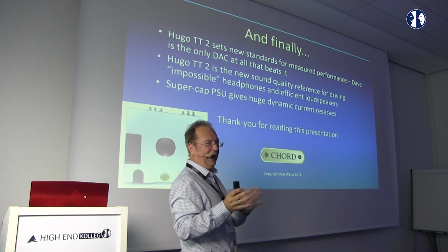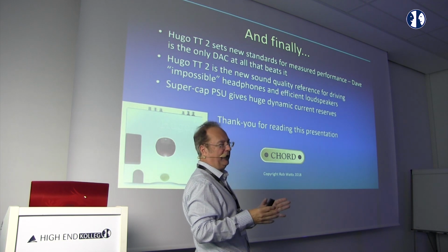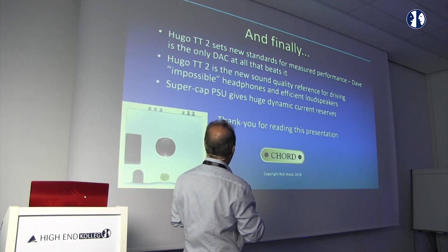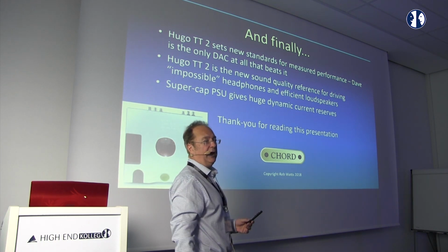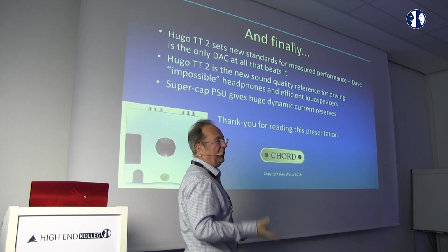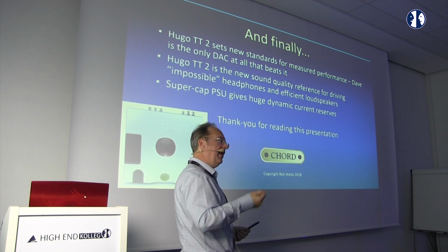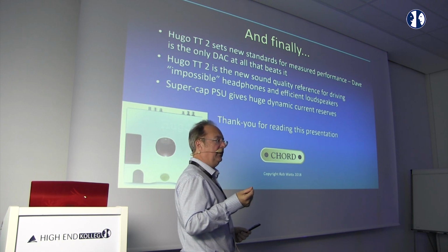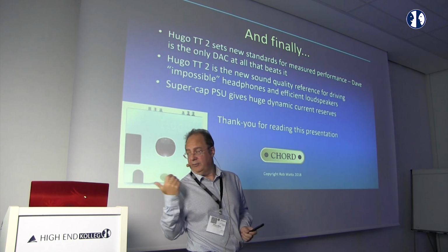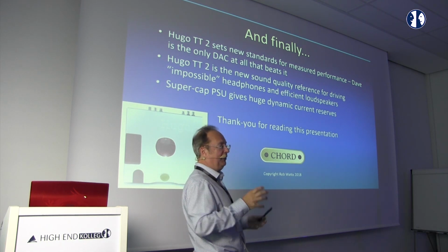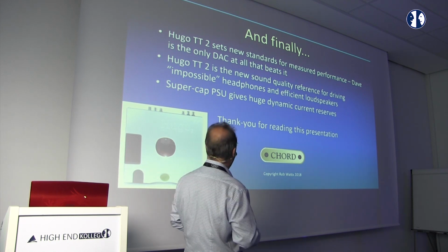This gives us an inkling for what's going to happen when the power amplifier project that I've been working on finally comes through to production. And the supercaps power supply gives huge dynamic reserve powers, as well as with the inductive filtering that I've put on the supercaps, I eliminate all the problems from the power supply that comes through. So when I plug the power supply in and off, and TT will last for 10 seconds, you can see there's no change in measurements at all when you plug the power supply in and out.